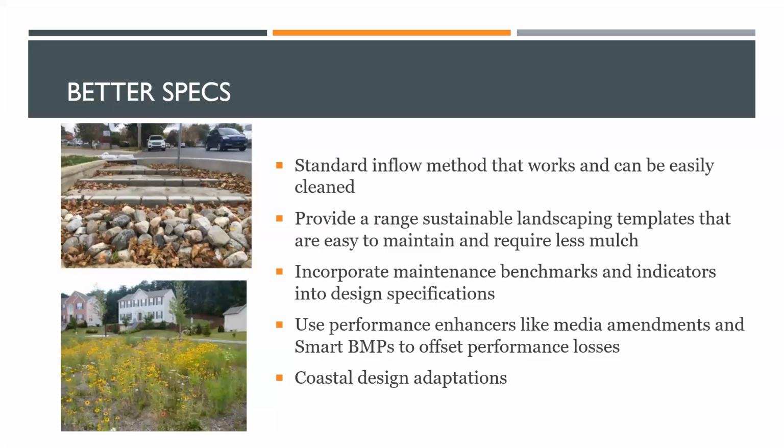There's also opportunity for changes to our specifications. I alluded to this a little bit throughout the presentation today, but the inlet is an area that I think is really ripe for some redesign potential. They can be a maintenance headache if you think about some of the cobble types of pretreatments and inlet designs. The curb cuts tend to be maybe undersized, or, because they're offline, maybe perpendicular to the flow of water. And so the water isn't getting in, especially in those larger events. So how do we redesign them or try to standardize the inflow to make sure that they're functioning the way that we want them to?